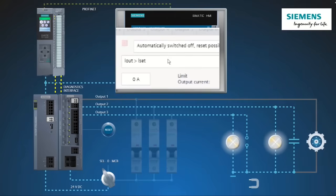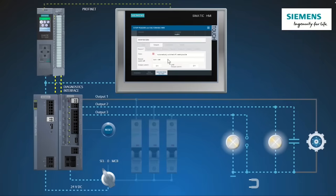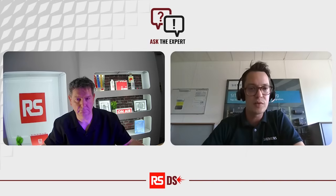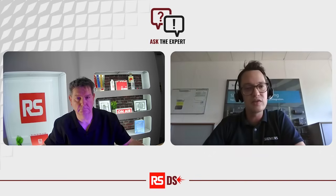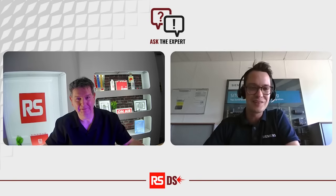And in that case, now you have two possibilities. Maybe you will go to the field and you have to open the electrical cabinet and reset the output manually. Or if you have a higher control system, you can reset the output via a reset signal from your PLC. I hope this was helpful.